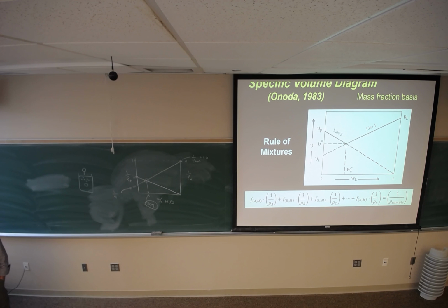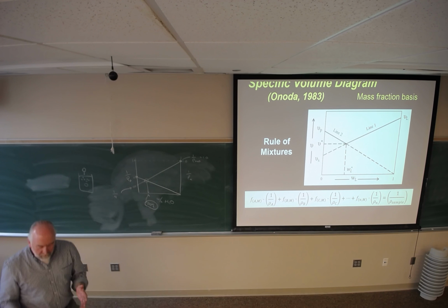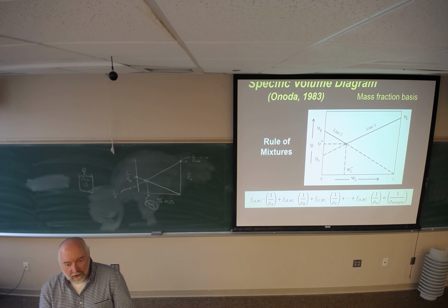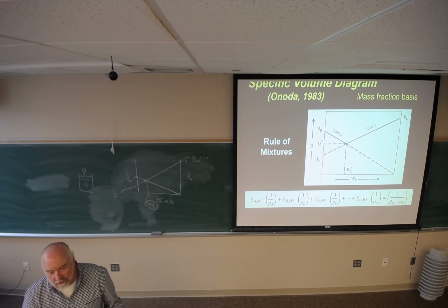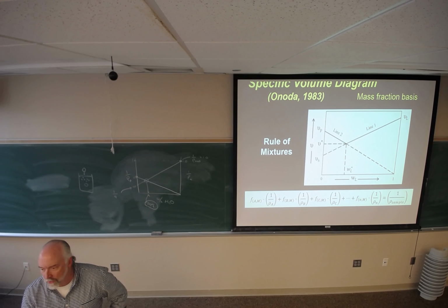All right, but you understand though that if I pack zirconia to 50%, the amount of water necessary to fill that pore space is 50% by volume. It's not 50% by mass because the density of zirconia is different. So what happens? If you look at recipes, we should make this a homework problem. Go find recipes for tape casting alumina or silicon carbide or zirconia or barium titanate. They're all different, because the density of those powders is not the same.